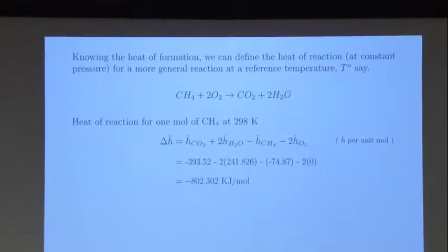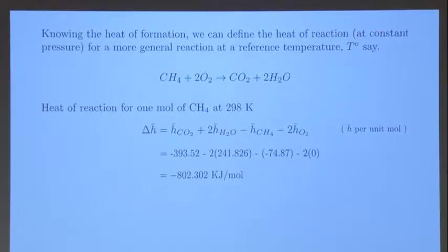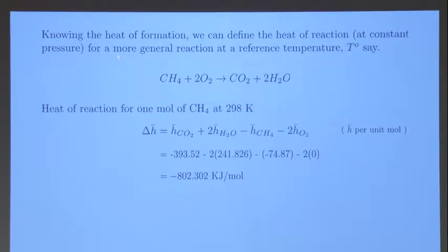Now, once we know the heat of formation of different elements, we can define the heat of reaction, but that's a heat of reaction at a given temperature. Let's say at the reference temperature T naught. So for example, if we have methane plus oxygen giving CO2 and water, the heat of reaction of 1 mole of CH4 at room temperature is going to be, now the bar on the H here is because it's per unit mole instead of per unit mass, just for consistency of notation.